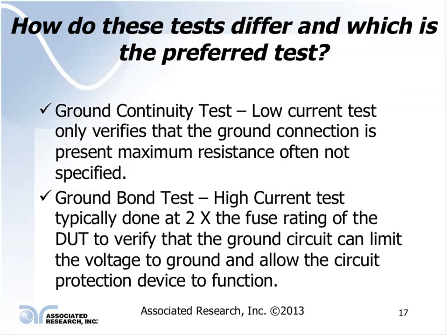Ground continuity test is essentially a low current test. It only verifies that the ground connection is present. The maximum resistance is often not specified. So this test doesn't really tell me that much.